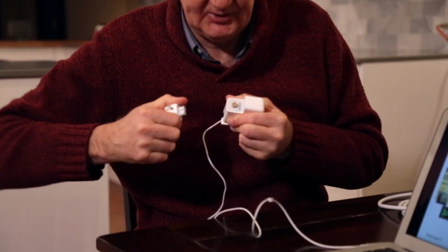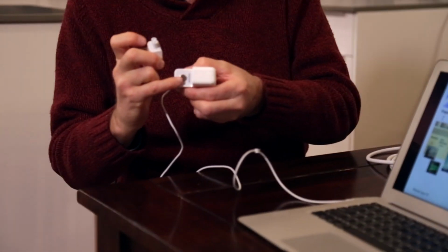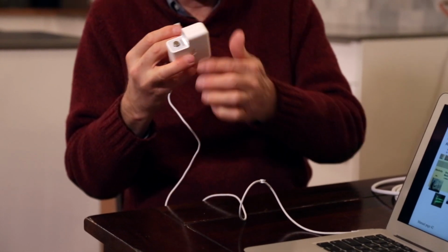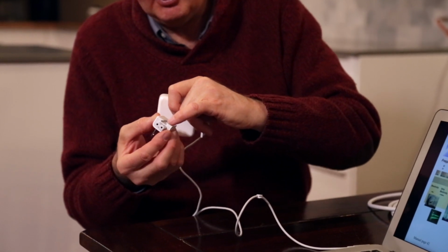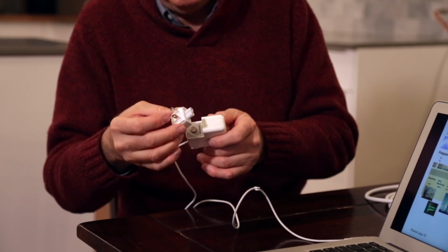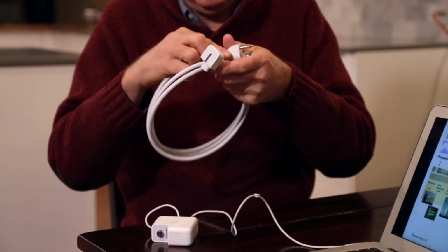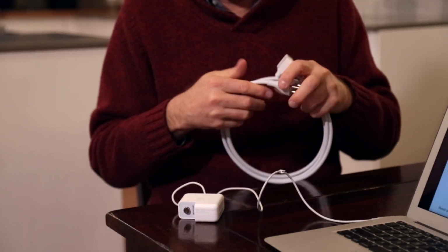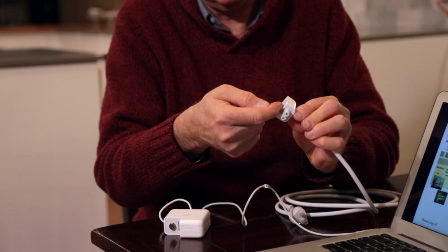So when it comes to Macs, what we recommend is that instead of using this adapter that comes in the box, you actually cannot put it on in the first place, or if it comes that way, pull it off, and you'll see that there is a grounding button here that goes to the chassis of the computer. But on the inside of this adapter, there is only plastic. There is no metal on the inside of this sleeve to come in contact with this because there's no ground prong here. However, in the box, you have this. And this is what should be used to power your laptop from Macintosh. This adapter has metal on the inside of the sleeve.